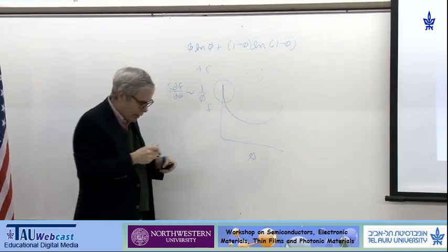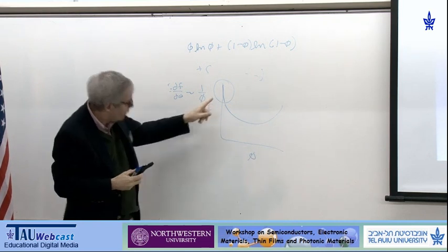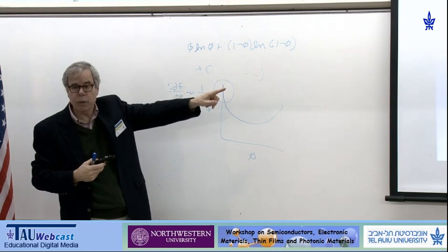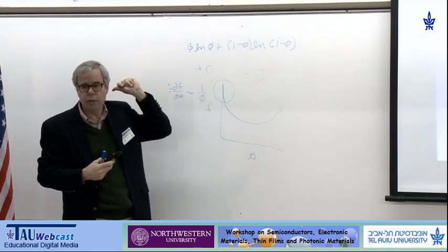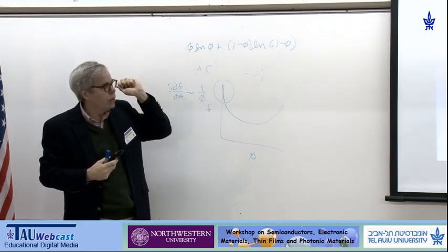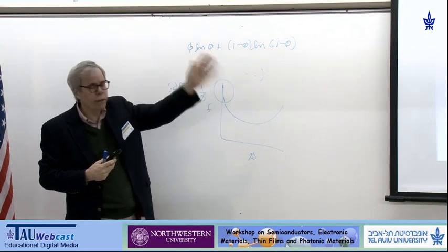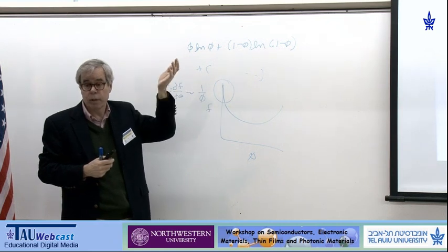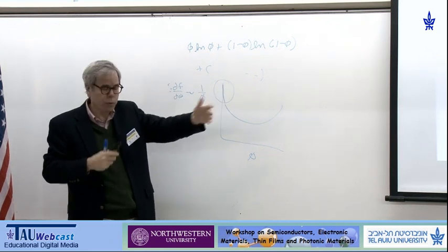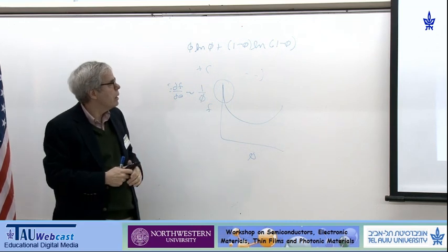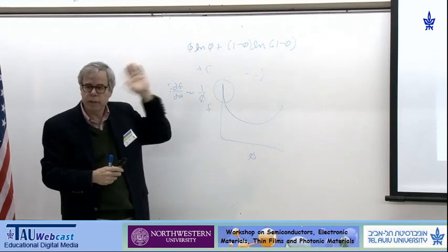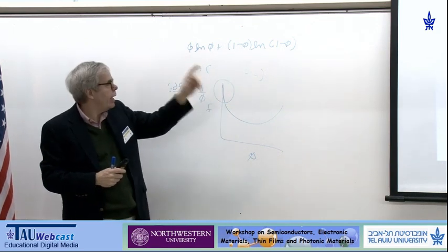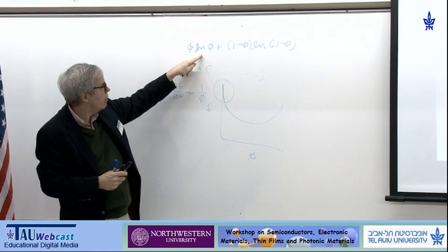This slope of infinity, 1 over phi going to infinity as phi goes to 0, makes implicit numerical methods of these equations extraordinarily difficult, and it's an unsolved problem. And so people will say all the time, you just write these nonlinear PDEs, especially if you go to a continuum mechanics group. They're very familiar with implicit methods, which basically make it easy to do time stepping. And say, well, just take these phase field equations and take my favorite finite element code, write an implicit solver, and as soon as you put in this thing, it doesn't work.